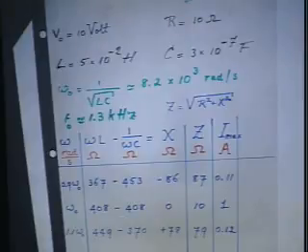When you're on resonance, and that is characteristic for on resonance, the omega L and 1 over omega C eat each other up. They annihilate each other, and so the reactance becomes 0. So Z now is just pure R, x is 0, and so the maximum current in this case is 1, because I chose V0 at 10, and I chose R 10.